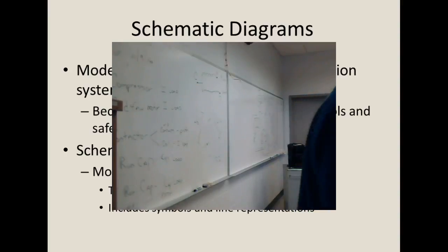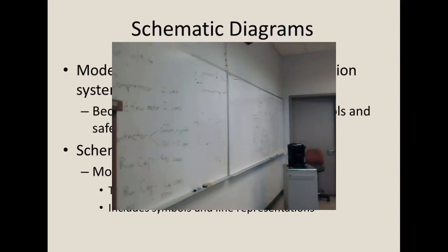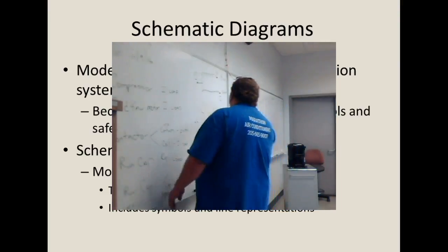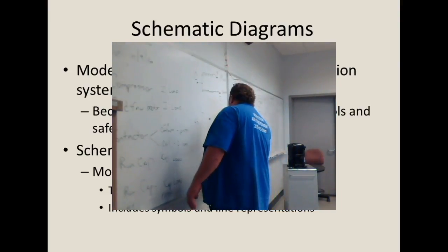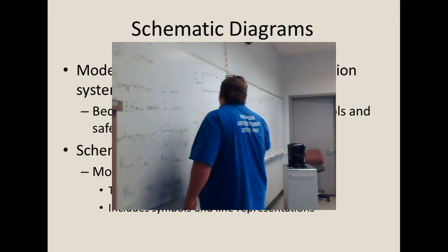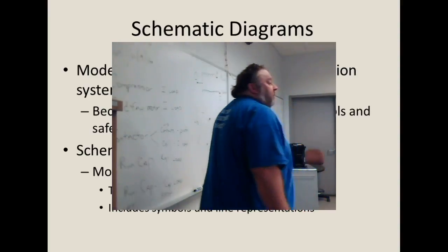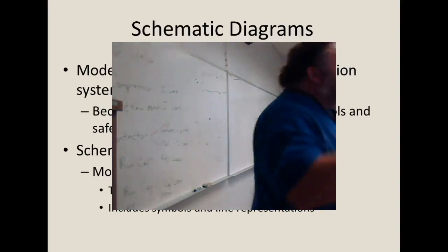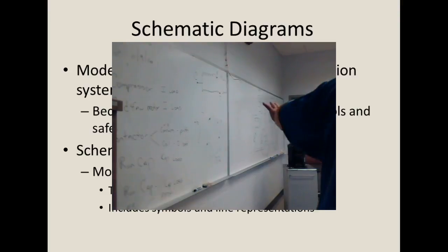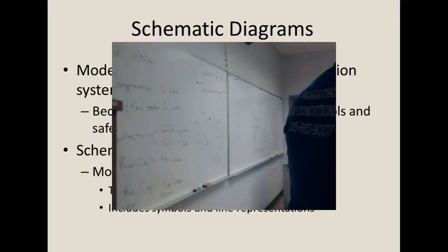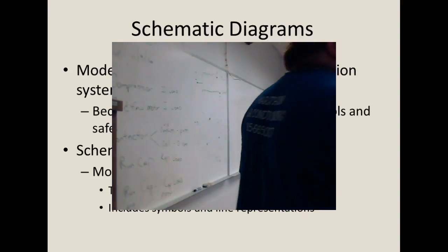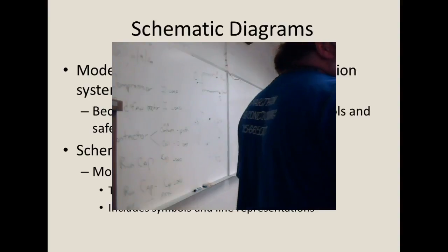Okay, so you get 3 readings, right? Somehow inside of this shell, I have a common and 2 coils. What I want you to do is, step 1, determine what the highest reading is. I have 3 readings. What's my highest reading? 3.2, right?